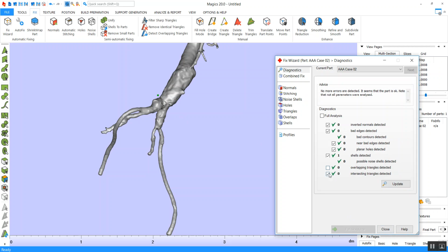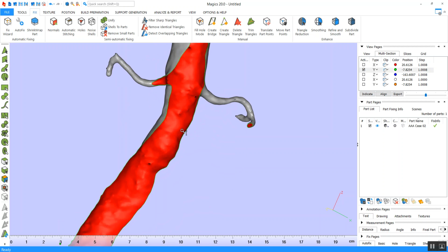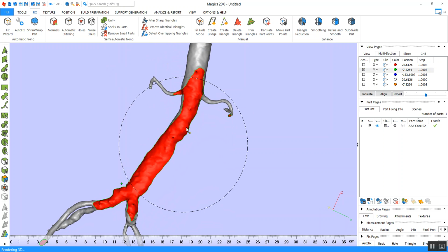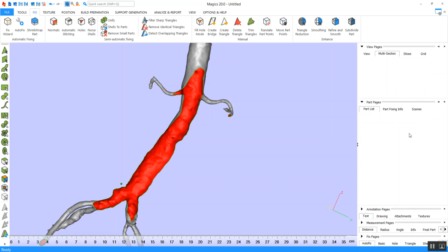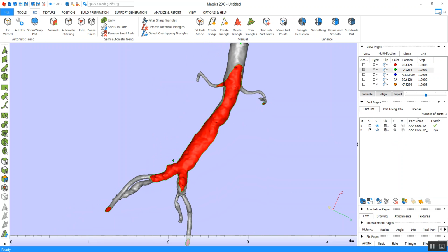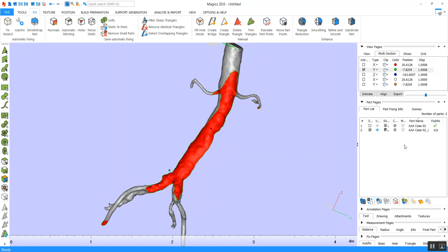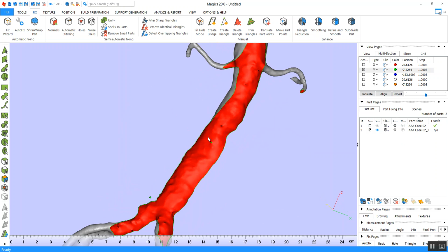I'm going to go ahead and close this. The first step, just so you can see, is I'm going to take a cross section. The very first step we're going to do here is take that shell and copy it. So Control C, Control V, and that should copy your file. Over on the right-hand side you can see we now have two objects, and I'm going to just go ahead and hide one. Let's take this first object here. We're going to call this the interior shell.